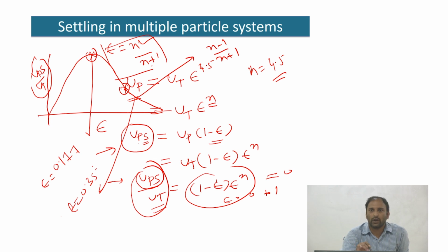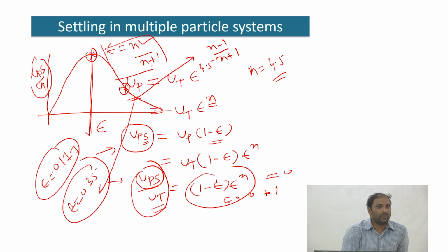The reason why I want to do this is because the type of settling that we talked about, whether sedimentation type 1 or type 2, depends on your initial concentration in the dispersion. So these numbers define limits where people are going to see very different settling behavior depending upon the initial concentration that you have in the dispersion.